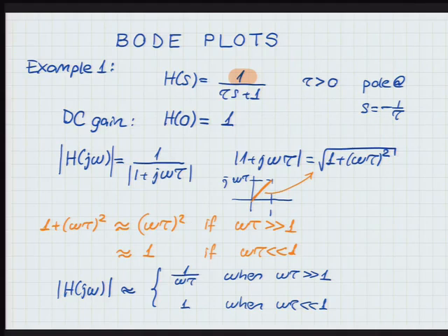So I'm not just going to plot the magnitude of H versus omega. Clearly, there is nothing linear or straight line looking there. Right? It's 1 over omega. It will go like this. But if I look at the logarithm of this, and that's what the so-called decibel scale does. You've heard that expression before, decibels?